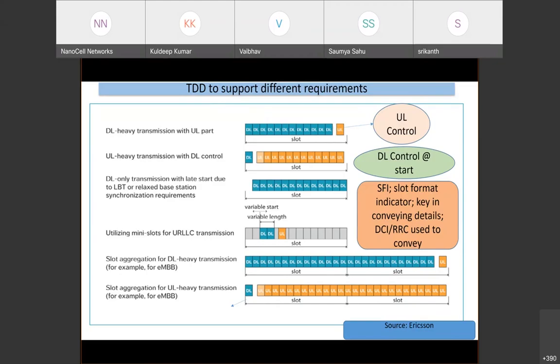But in the case of 5G, we don't have that configuration business. We have more of a, according to the nature of the situation on the ground, we could be heavy on downlink, heavy on uplink. We could even be offset from slot time because of carrier sensing kind of limitations which might occur in unlicensed band.